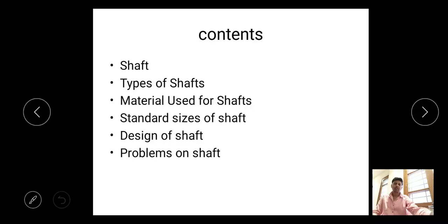That is the stress strain diagram when you are applying a load on a component using a UTM, universal testing machine. Then what graph you are getting for mild steel, we have elaborately studied that. What do you mean by proportional limit, Hooke's law, then what is elastic limit, what is ultimate stress, that is the ultimate strength of a material. Then we studied the breaking point.